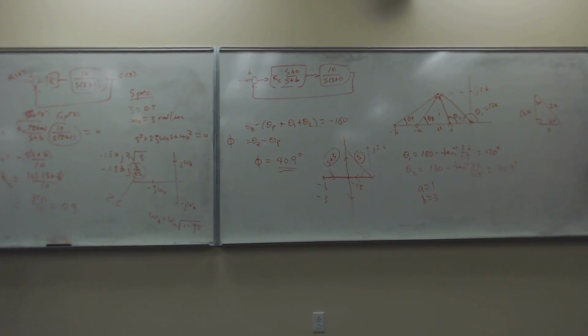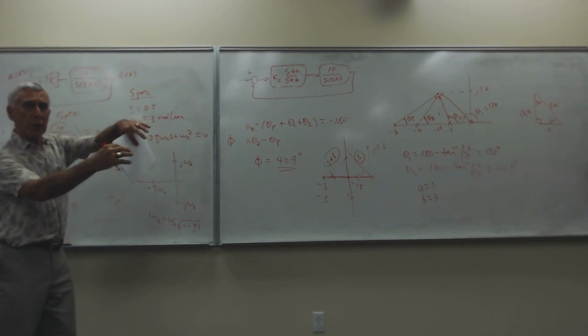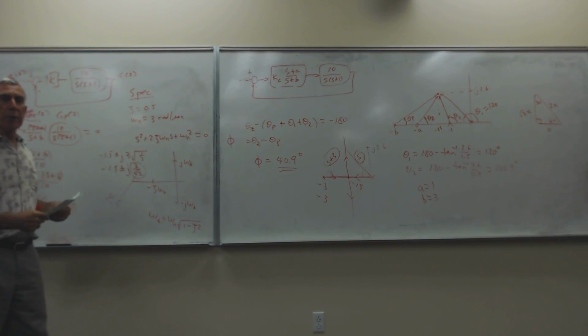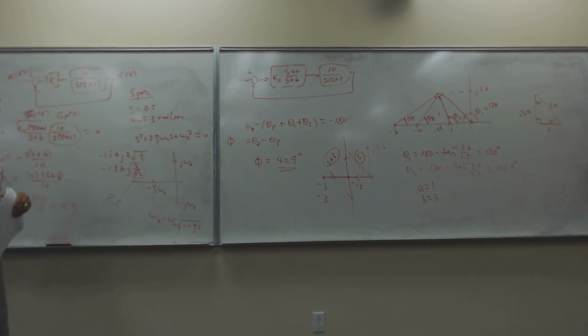Now, what we can do is draw the root locus, right? And we already drew the root locus. We basically, when we considered the lead compensator, the root locus is being pulled, attracted by the 0 of the lead compensator. And it will, in fact, go right through that point there, the desired closed loop pole. I can show the MATLAB for that.